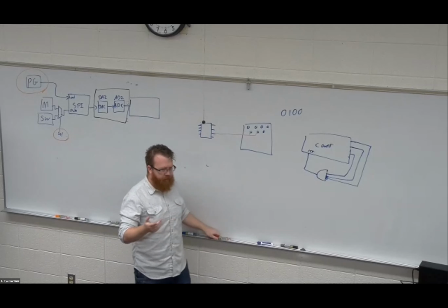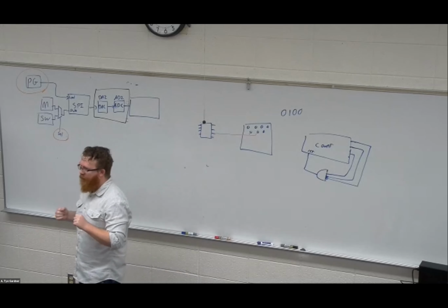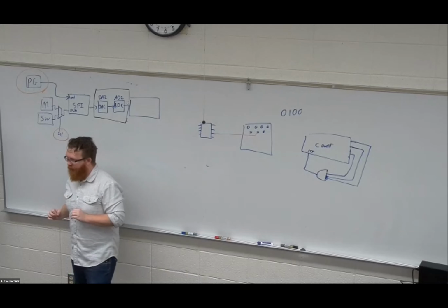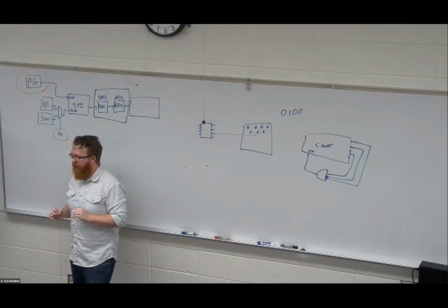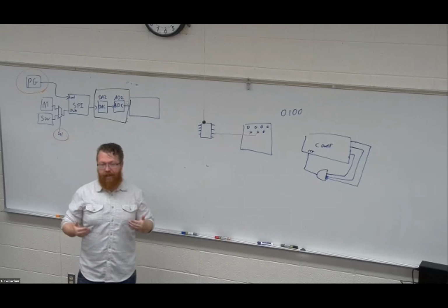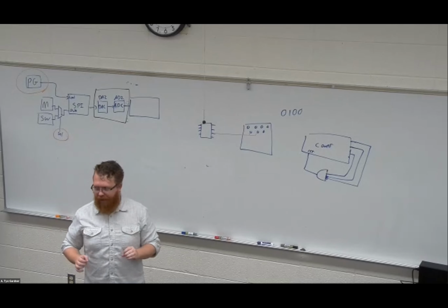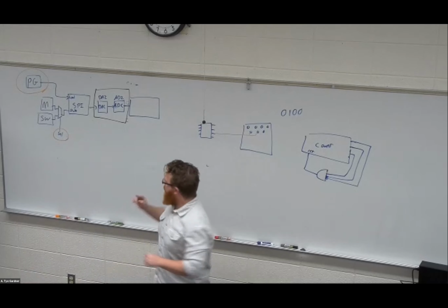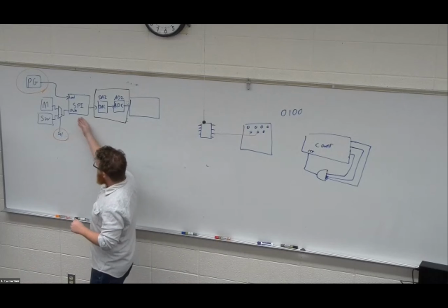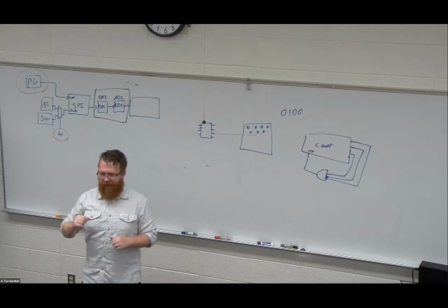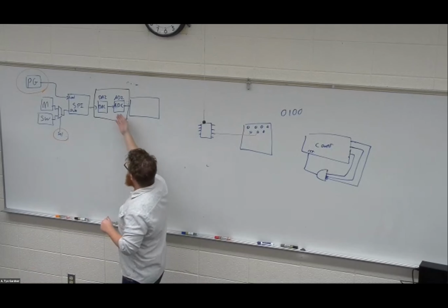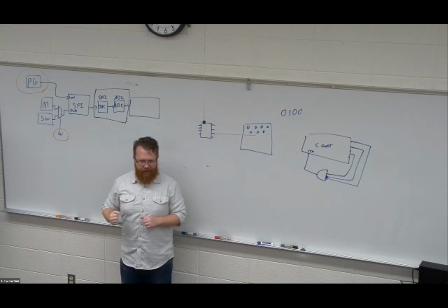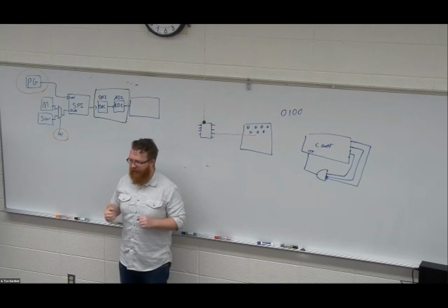Like the seniors that I have working with me on a senior project right now, they use I think every single one of their IOs on their FPGA. And so you have to take that into consideration: am I going to run out of IOs? So say that I am. Say that I've designed this system and I built a SPI that is controlling 30 DACs. And now I need an ADC to record 30 DACs, right? That starts scaling up. I need lots and lots of signals.